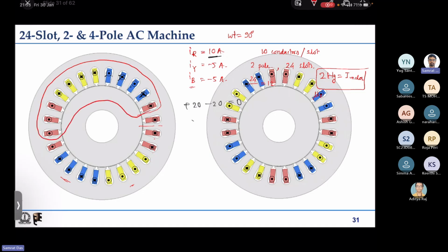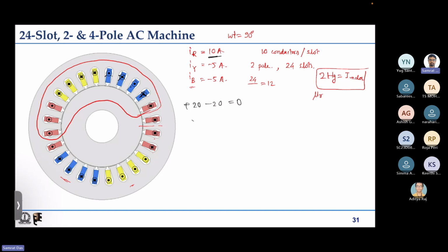then if the same calculation is done, you will be able to see still these blue conductors for the same currents, for the same instant, omega t equal to 90 degrees, same currents. So this blue cross and yellow dot, they will cancel each other. One R cross will be cancelled by one R dot, so effectively this will get added and this will get added. So we'll have some addition. So this is 20 and this is 20, this is 10 and this is 10.